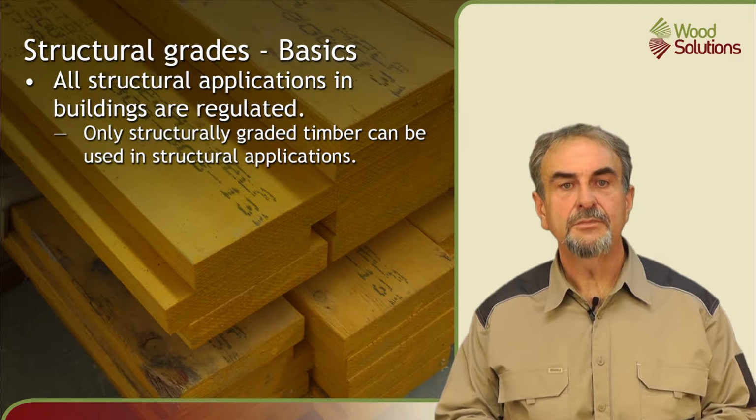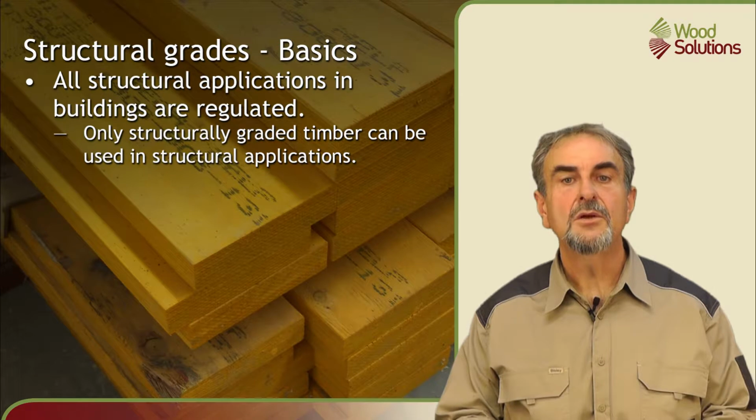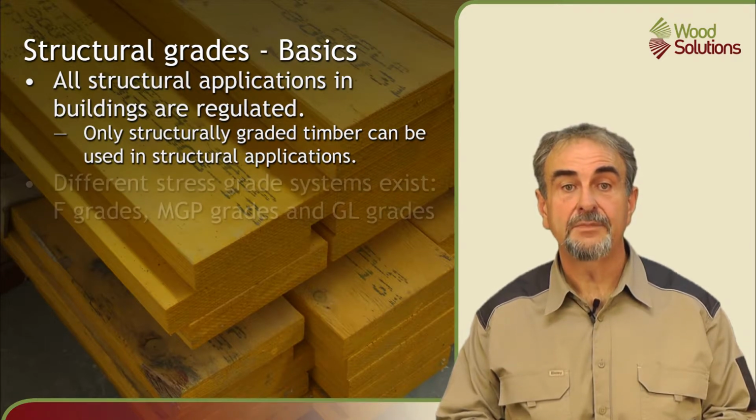So each structural timber element must satisfy the requirements of the engineering design standard for the load that it is expected to take. And its structural properties must be determined in accordance with the structural grading standards or by any independent engineering certification. In short, only structural grade timber is allowed to be used in structural applications.